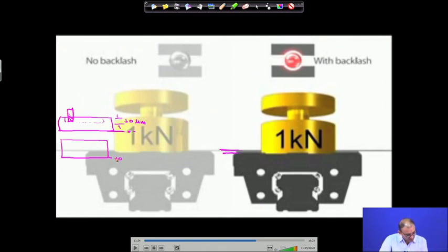Consider that the deflection is 10 micron, so this is minus 10 micron down. Your tool is still here and you assume it has gone 50 micron into the workpiece from the top surface, correct, but your top surface has shifted down. This is what you actually want to cut, but because of this deflection, what you are cutting is this one.